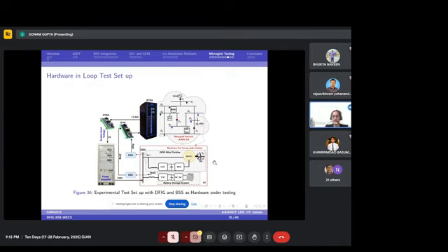with the hardware test setup, and we performed the same thing for the grid connected as well as the islanding mode. Since this whole network is connected to the grid, if switch one gets disconnected, then the wind turbine will still remain connected to that bus, or in other terms, the bus will be able to maintain the voltage throughout or not.